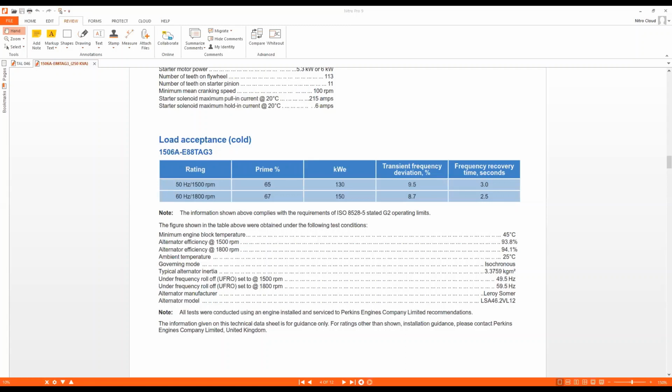Typically speaking, if the requirement is for the genset to accept 100% load in a single step, I'd personally go with oversizing the genset even a bit, and I'd make this 100% equivalent to 90%. Okay, although some gensets do take this 100%, but it's really rare and it's highly not advisable. Okay, guys. Okay, excellent.